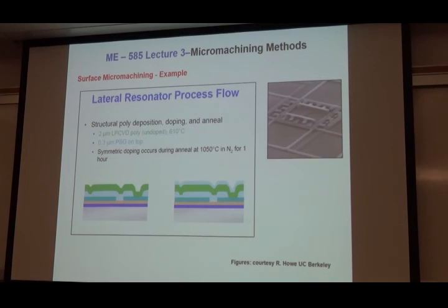Does it harden quickly? Oh yeah, this will happen within minutes actually. So remember, LPCVD, chemical vapor deposition, right? It comes like this, I told you, and then fills the hole within minutes. As soon as you reach the temperature, it's going to start. But the way it's going to fill it in is not going to be a straight line. This is a mechanics problem. Okay. All right, so we have this.